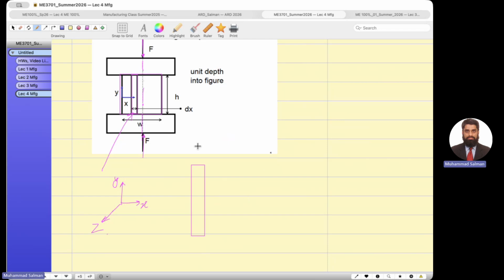Let me show you over here. We assume this is the forging force pressure. And then over here, when the material moves outward, there is stress also here. Stress is different here, and this is my applied pressure. So the friction force is opposing the flow. The friction force is mu times the applied pressure.